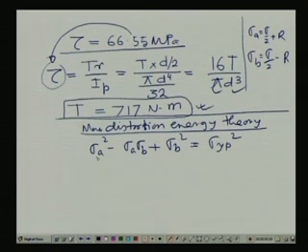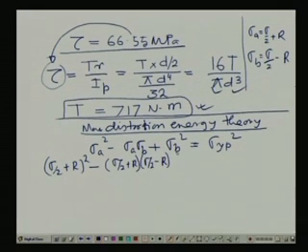It comes out to be the long expression: (sigma by 2 plus R) whole square minus (sigma by 2 plus R) into (sigma by 2 minus R) plus (sigma by 2 minus R) whole square equals sigma yield point square.